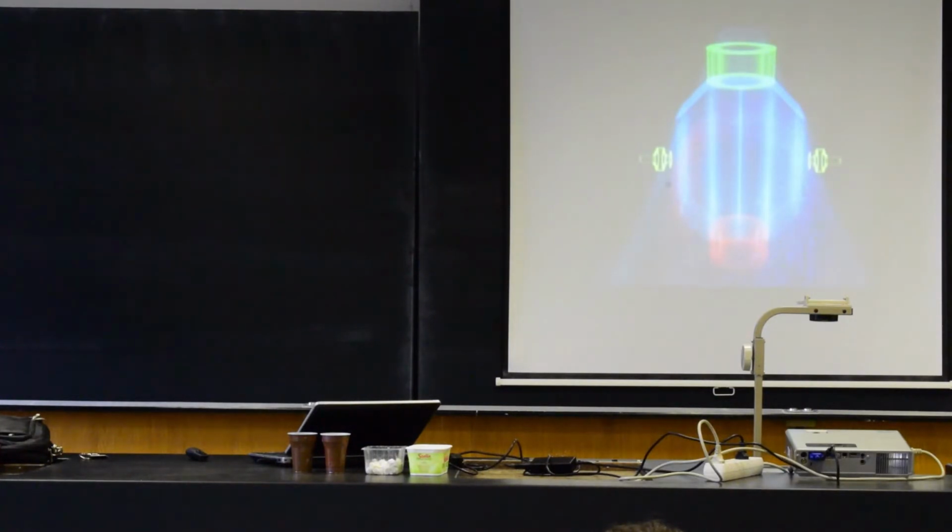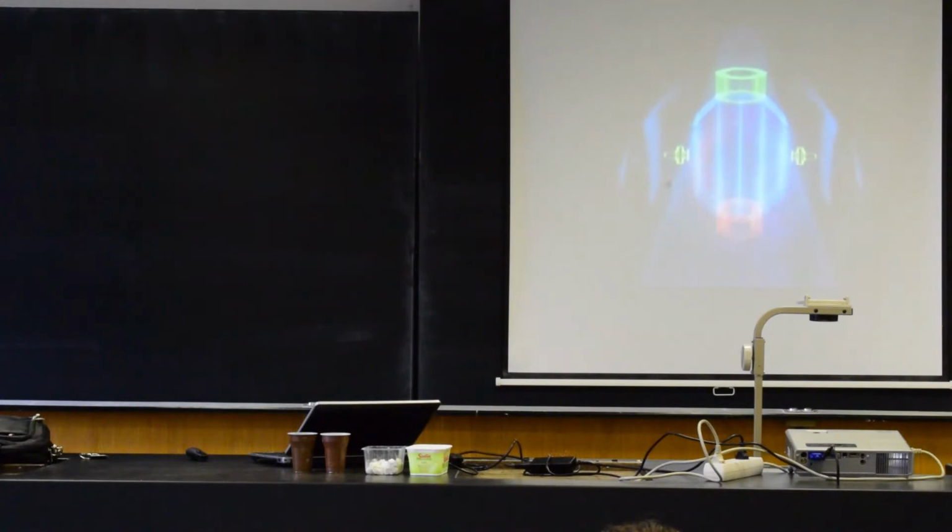successfully used for this purpose is to create the magnetic field with a pulsed direct current. To do so, the polarity of the magnetic field is alternately reversed, illustrated here in slow motion. The voltage picked up on the measuring electrodes now constantly changes in polarity. As a result, all constant interference voltages can be eliminated.